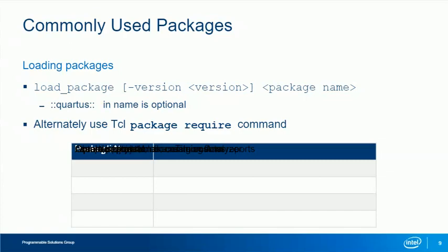Alternately, you could use the Tcl command, package require, to load any of the packages, but the Quartus load_package command makes it easy to load and unload different versions of the Intel Quartus Prime software packages.